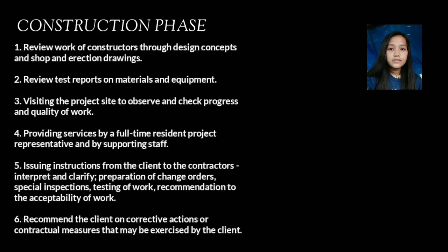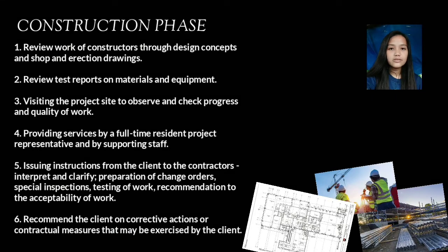Construction phase. Services in this phase include consulting and advising the client during the construction. We have review work of constructors through design concepts and shop and erection drawings, review test reports on materials and equipment, visiting the project site to observe and check progress and quality of work, the location, providing services by a full-time resident project representative and by supporting staff, issuing instructions from the client to the constructors, interpret and clarify, preparation of change orders, special inspections, testing of work, recommendation as to the acceptability of work.